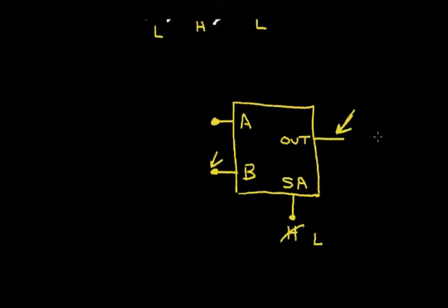So this gives you some idea of the different circuits that we can do. Just starting with an inverter and a CMOS switch, we can turn that into a tri-state driver. And we can take the tri-state driver and an inverter and we can create a latch circuit to store data. And then just making a very simple change to that latch circuit by removing one connection, we can turn that circuit into a MUX or a multiplexer.